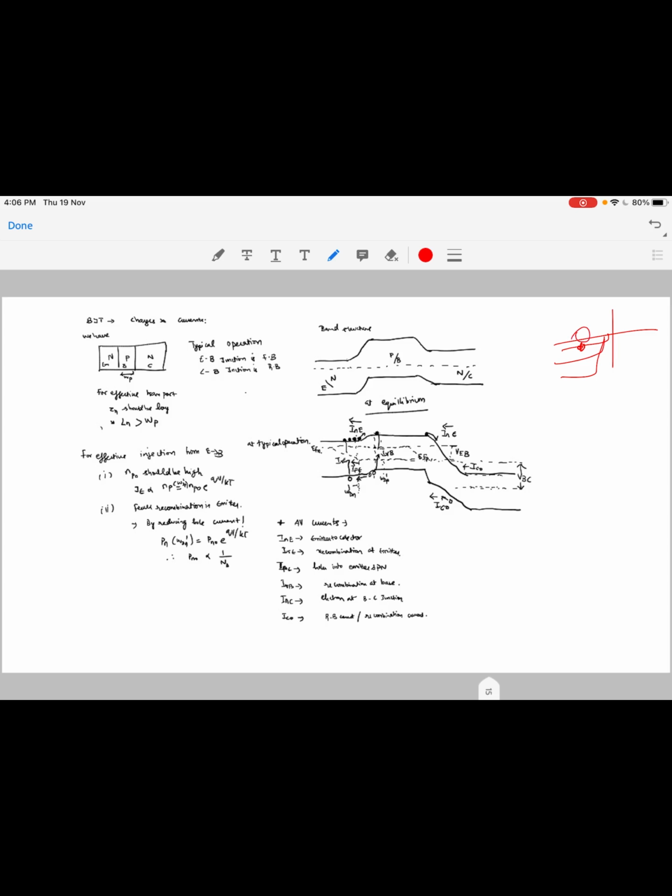And this is the reverse bias junction. This is basically your base collector junction, and then you change the emitter injection to jump from one current level to another. So this is an ideal current source, because the current value does not change with any change in the bias that you have applied until you reach a particular point. That's the difference. So there are several currents in a BJT.